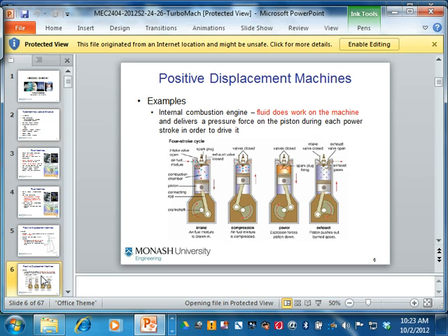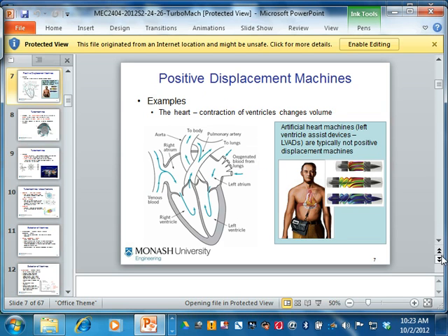This one is an engine, so there's other things going on in it. But you don't have to have other things going on in it, like an air compressor. They use it for making compressed air everywhere, in workshops and factories and so on. It's actually normally a piston with a crank slider arrangement to pump the piston up and down. Valves opening and closing make sure that you take in air, you compress it, then you open, and then it siphons to a pressurized tank or somewhere.